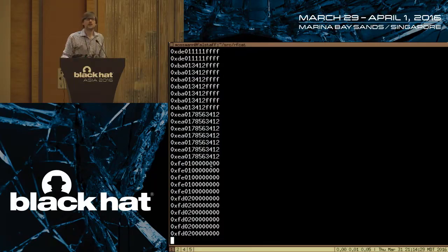Any other questions? Yes. So the stuff that I did with the HackRF could have been done with the RTL SDR dongle. The things that I did with RFCat cannot be done with the RTL SDR dongle, and that's in that category of maybe in the future we can make better tools for SDR reversing. Like we could make something like RFCat built on top of an SDR platform instead of built on top of a wireless IC platform. That's totally possible. It's just that nobody's done it yet.